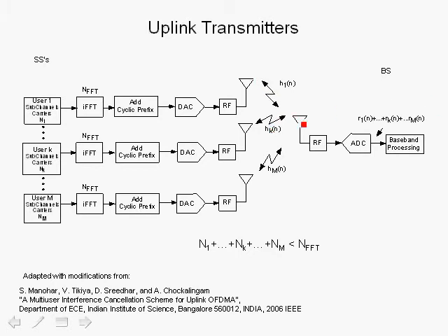We have M subscriber stations, M, for example, 10: subscriber station number 1, subscriber number K, or M, or as we shall refer to them, user number 1, user K, or user M. We've simplified the transmit chain on purpose, and what we're showing is the fact that user K, for example, has been allocated a number of subchannels, and of course, as we know, each subchannel has a number of carriers, for example 48.